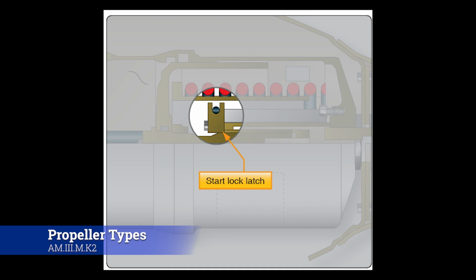Now, one of the other features, it's not necessarily its own independent type of propeller, but it is an independent feature of propellers: its ability to feather. Feathering essentially is whenever the blade goes to 90 degrees and has the least amount of resistance against the forward air, the relative wind, I guess is the right way to say it. They do this so that if an engine were to fail, you should be able to feather it and reduce the drag of that prop on the aircraft and allow you to get on the ground.